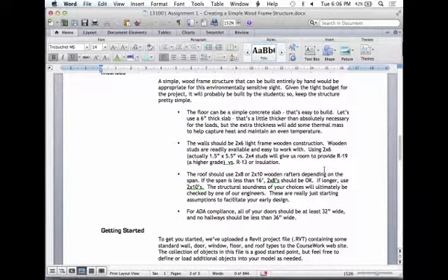Okay. There'll be layers on the outside and layers on the inside. On the inside, often in structures like this, we'll have gypsum wall boards. It could be lath and plaster, or it could be wood, but gypsum wall boards are a very cheap, inexpensive material. So there might be a half inch of gypsum wall board on the inside of the core. Then on the outside of the core, there's going to be a couple layers.